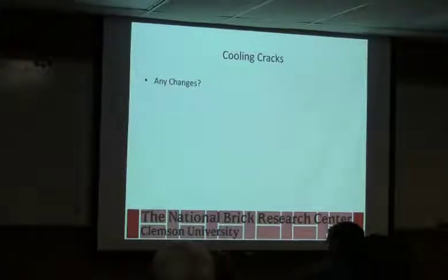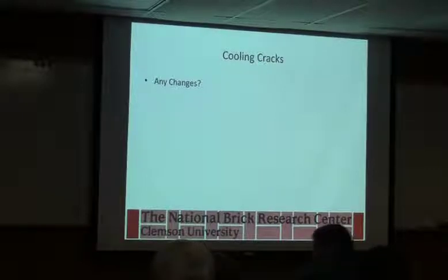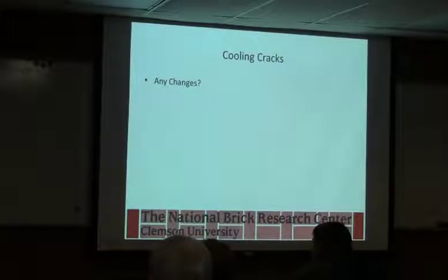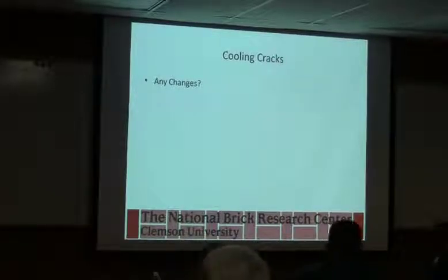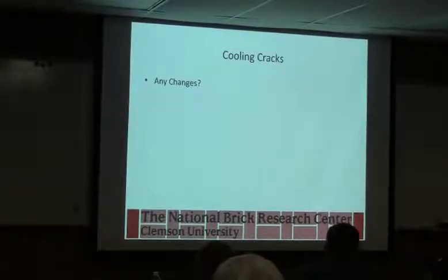Cooling cracks. Can you decrease the amount of damage done by making finer quartz? More often than not, when I'm going through that temperature range, I'm giving more time for things to move slowly through it. You're going to get movement in the product as you're changing the size. So if you go slower, it gives time for the particles to shift around a little bit and reform their glass bonds and get happy.